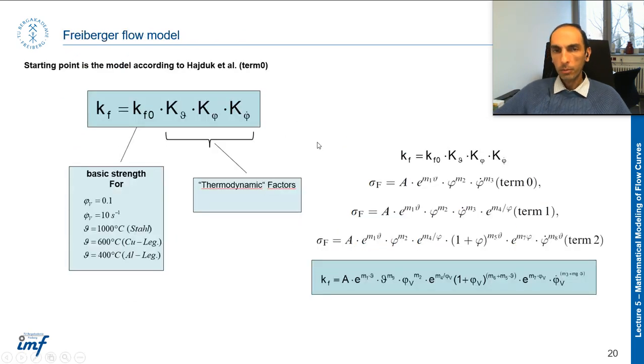And the final model is the Freiberger model. Which is, of course, important because it was developed in Freiberg, and as I know, the idea started according to the research of Hadfield et al. almost 100 years ago, I think. The meaning of the terms, we talked about it in the slide. We were talking about the dislocation density, precipitation hardening, and the other parameters.